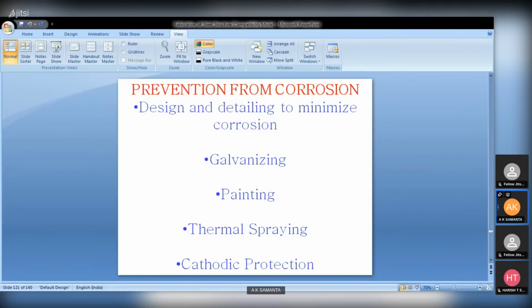That's why all our water lines, even electrical transmission towers or railway electrification towers, those towers or poles, are subjected to galvanization. If properly galvanized, the corrosion will be resisted for at least 25 to 30 years. In the morning, you asked the question how steel sections in a toilet or bathroom get protection from corrosion.